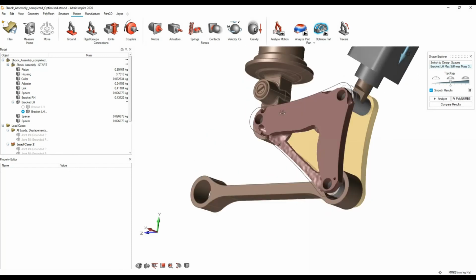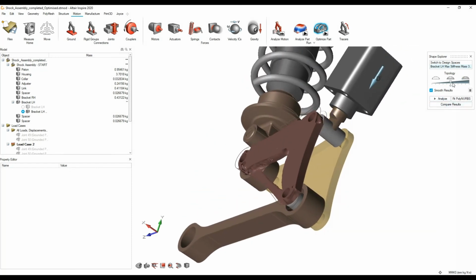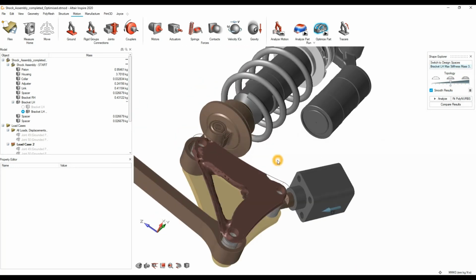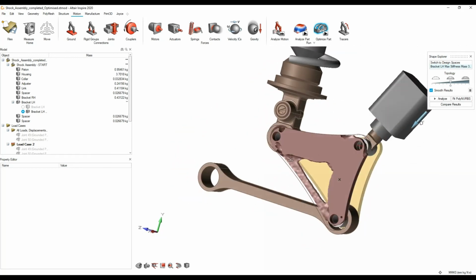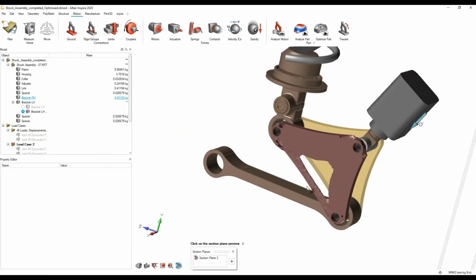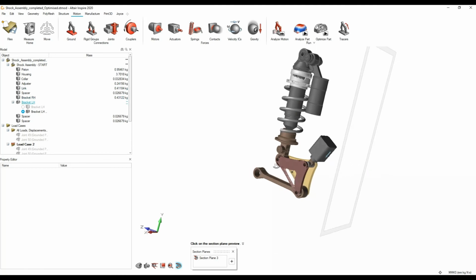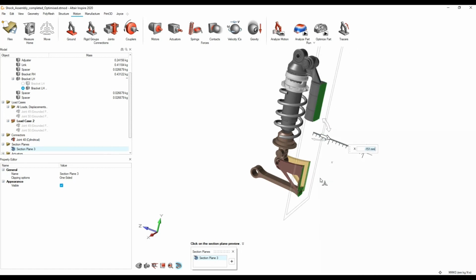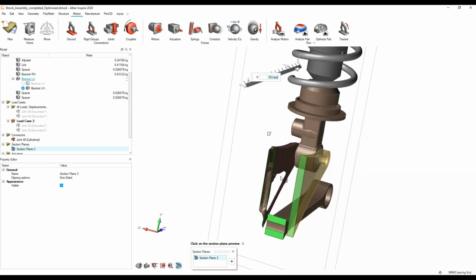So if I just head back into Motion, and where we see optimization itself, you have a topology slider, so it tells you exactly the first areas where you really don't need material. So it takes away all your redundant material, and you can see exactly what kind of shape it recommends. And straight through here, what we could do is implement, let's say, a cross section, and within this cross section itself we can drag it so that we can see exactly what our optimized shape looks like.